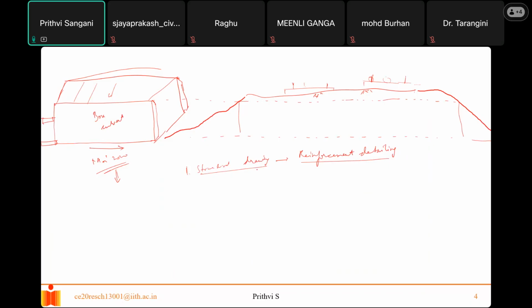And once you have constructed it, there are also as-built drawings. You need to give an as-built drawing. It usually has both architectural and structural details. It should include how much reinforcement you actually placed and what the architectural dimensions are. Architectural in the sense of your cross-section details: if your slab thickness is 150, but after laying your slab the thickness is 151 or 152, you will exactly mention those details there.